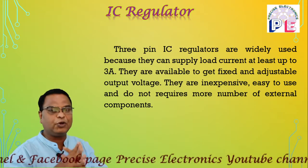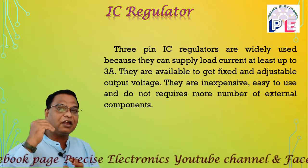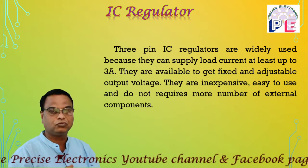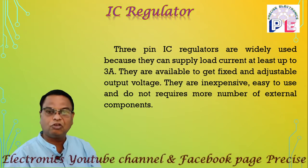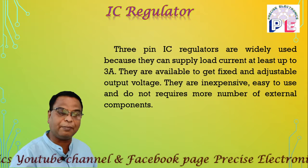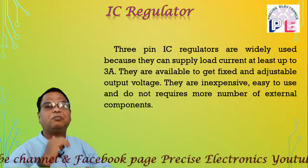These 3-pin regulators are widely used because they can conduct a load current up to 3 ampere. 3 ampere is a sufficient current for our electronic appliances. So these IC regulators can handle a current up to 3 ampere, and they are available in fixed and adjustable modes.